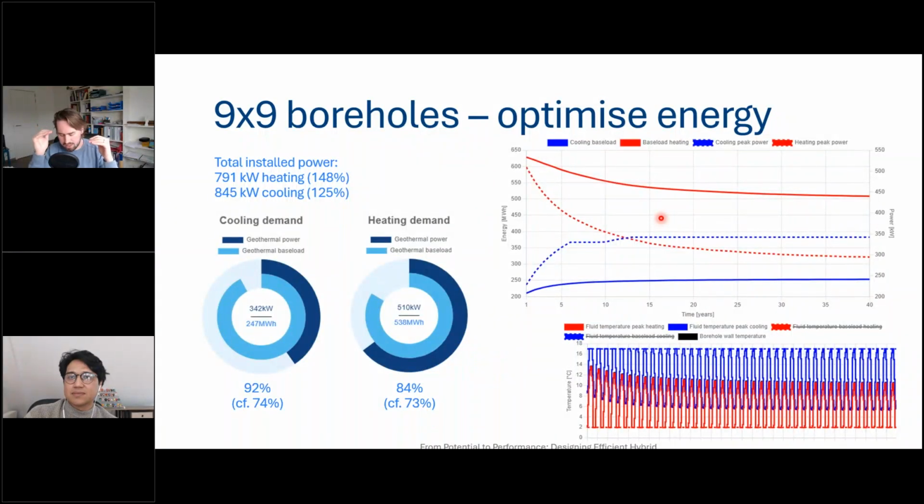So if I decrease my peak cooling, how much energy can I still extract? And that's what it does for all the months in the simulation period. You have an hourly input, but you work in the methodology with a monthly resolution, which is, by the way, just for numerical reasons. You can do it hourly, but then it will take an hour to calculate and not 1 minute.